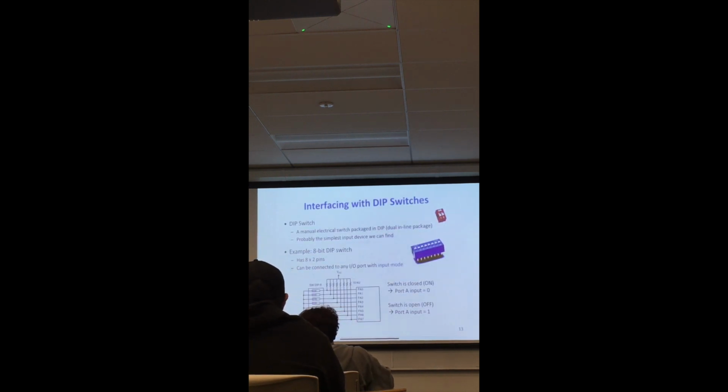And similarly, interfacing with dip switches, right? There are multiple ways to do it. You can use these as pull-up resistors or pull-down. So there are different ways to connect it and to actually use it to connect the switches. You will have sort of positive logic or negative logic, depending on how you connect it.